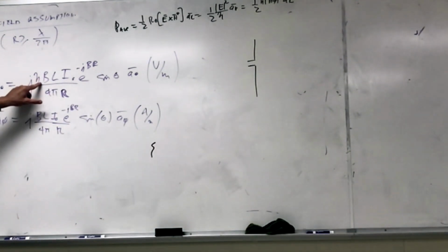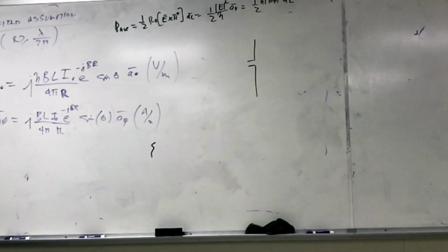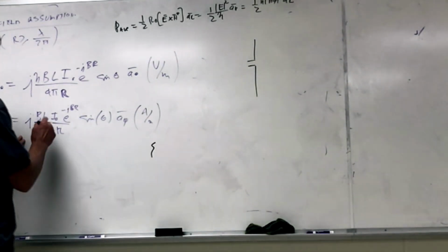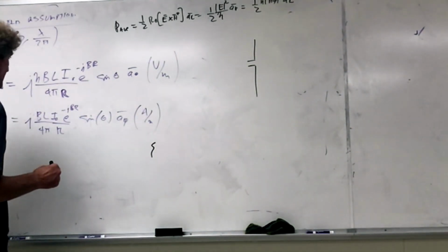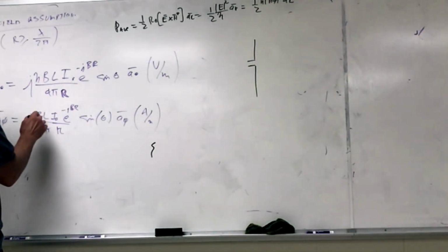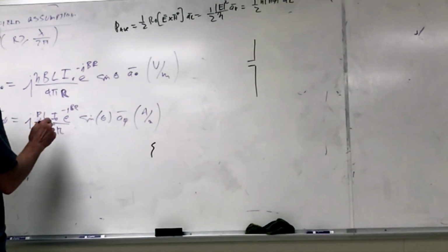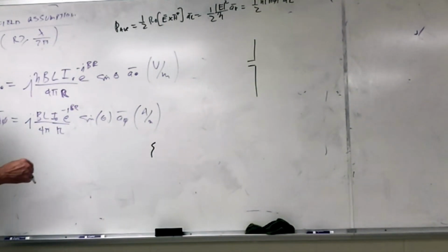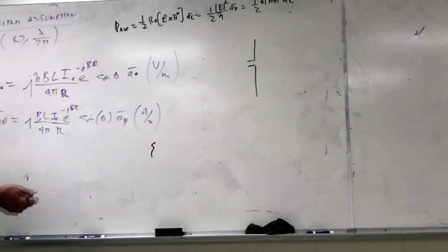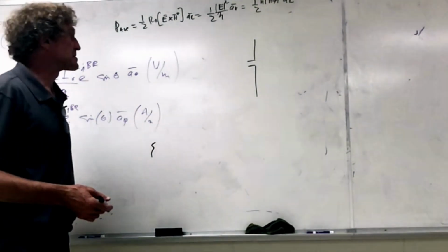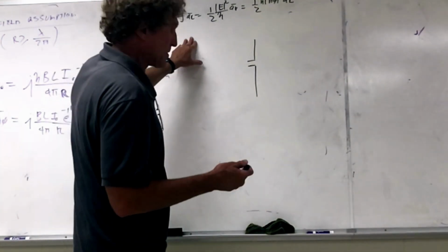There's the intrinsic, right? Oh, H field, right, that's H field. Oh, I'm missing the H field. That's right. So beta is 2 pi over lambda times L, so you're going to get 1/2 L over lambda, I naught over r, and then e to the minus j beta r over r, sine squared. You might as well do this. I'll put it down right here.